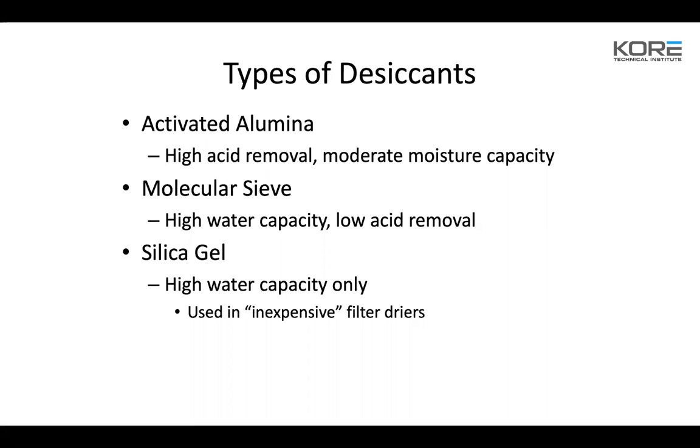So anytime you're trying to remove moisture or acid from a system, you're really going to want to make sure that you change to a high acid dryer, and then always go back in with a regular dryer, because that's going to be your permanent fix. Are there any questions there on burnout or water situations?